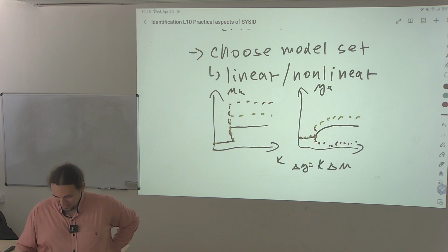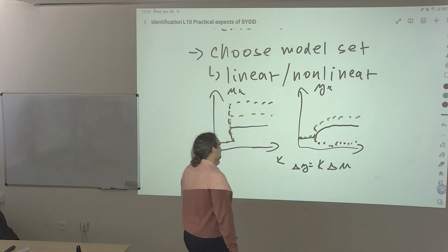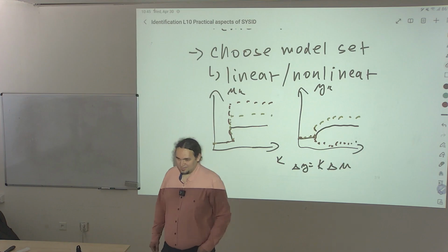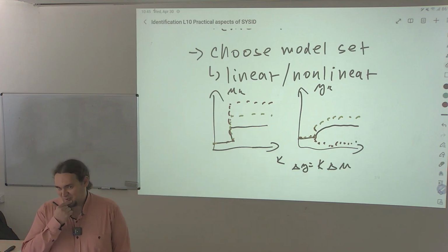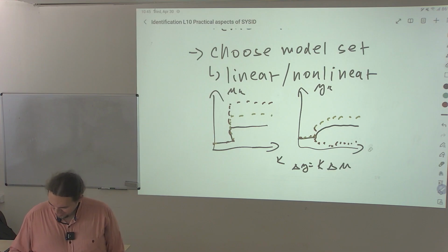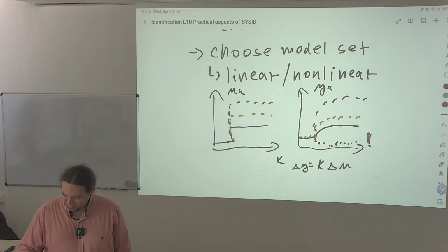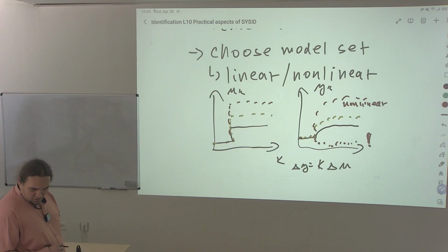That case can be nicely solved with integral control action. This one is much harder. It's basically impossible to control it with a linear controller. So even the LQR, none of the easy stuff would work. So that's a red alert if you see this behavior. This one is non-linear but bearable.